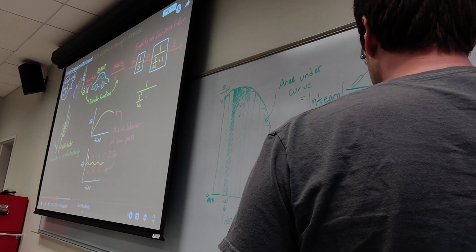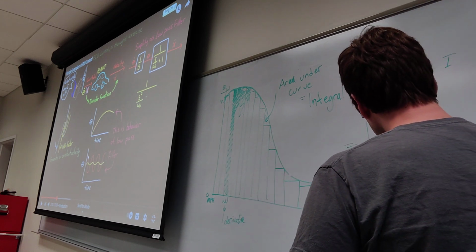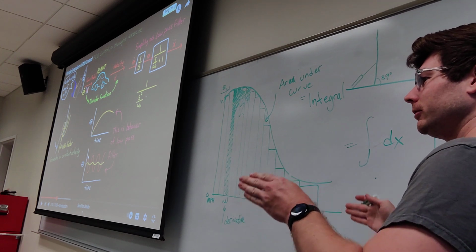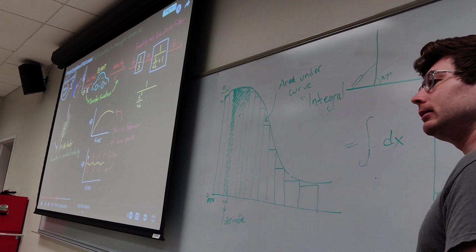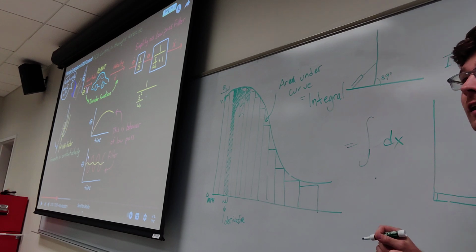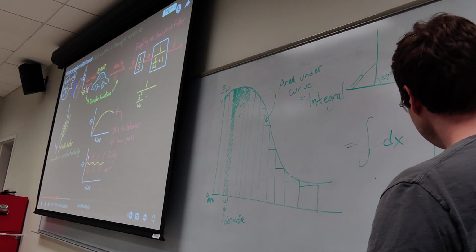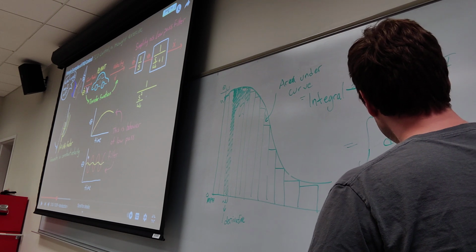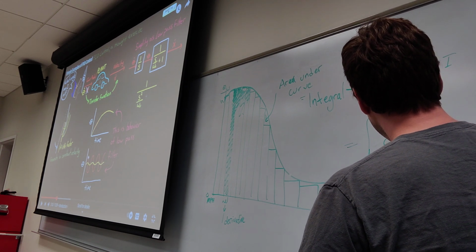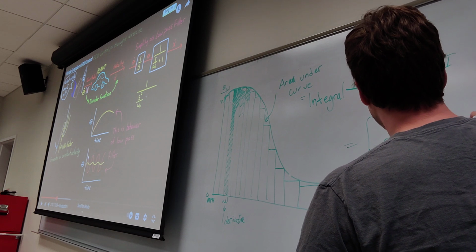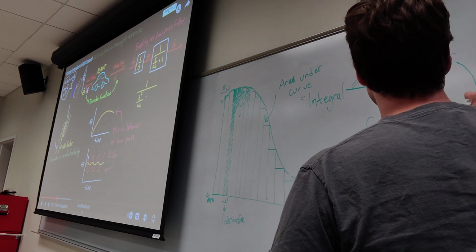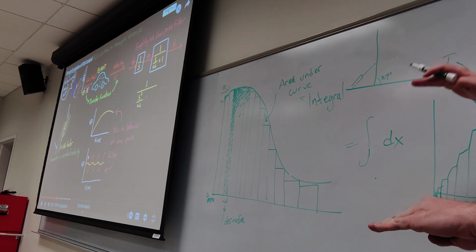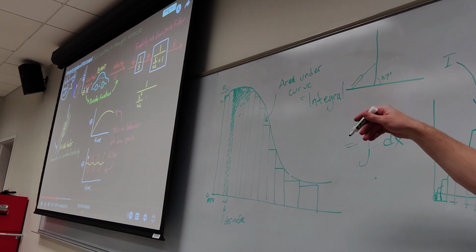So the I controller, the integral, is what if we added up that little error so it started to accumulate. Over time, hey, we've had this error for a really long time. Maybe that's important. That's kind of what this term is doing. If this little error is here, and still here, and still here, it will integrate and integrate and integrate. So our I term, the thing that's saying we need to correct our action, grows and grows and grows while that error is still there.